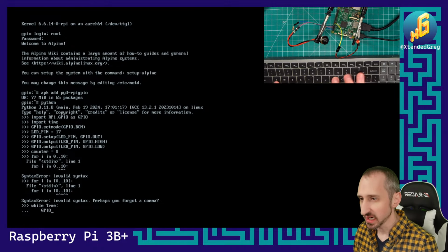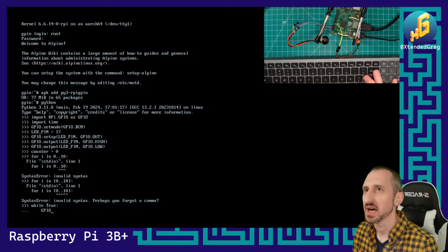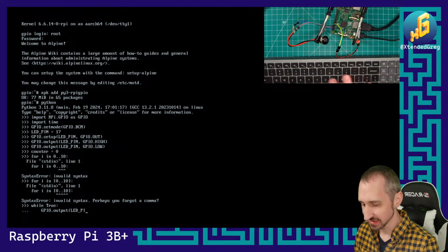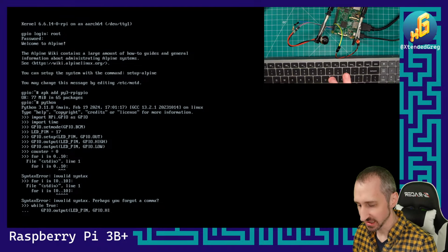So we're going to do GPIO.output. I have to spell it right, otherwise it will error. And we'll do LED_pin, GPIO.HIGH.